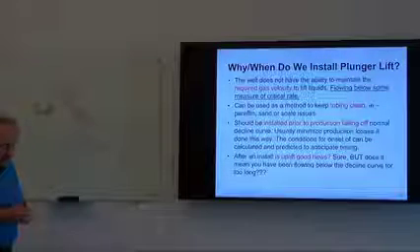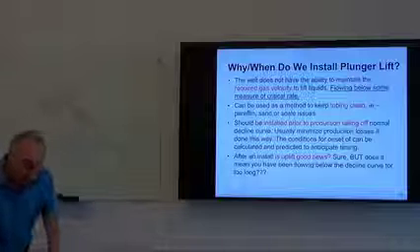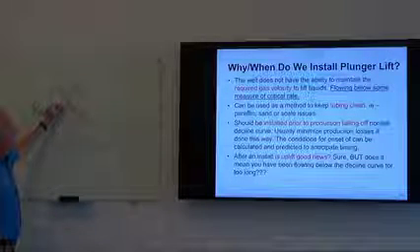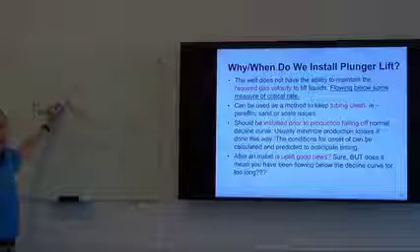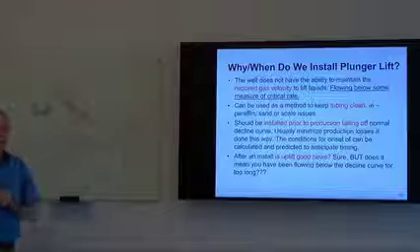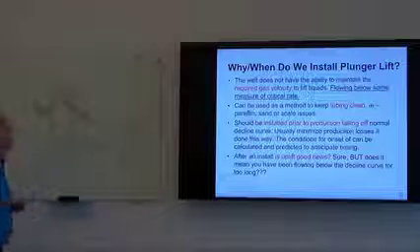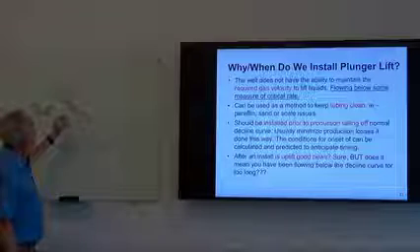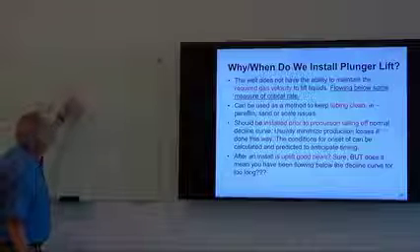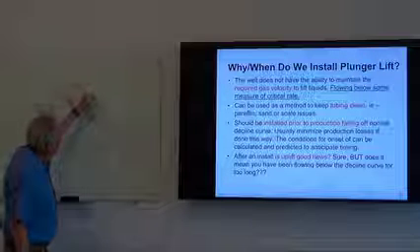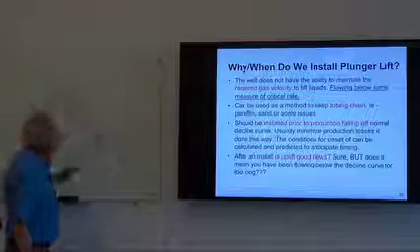And what we might do instead is recognize when this condition is going to begin occurring and start to intervene and add our plunger lift at this end of the life cycle of the well. And we might here run, for example, in today's world, a continuous run plunger.